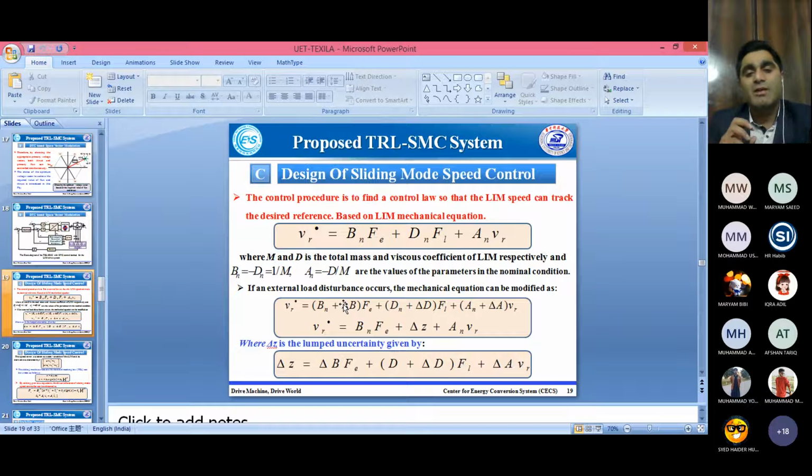So the work of the control law or reaching law is to bring the state to the reference value. So we have to design one equation for the control law, another for the sliding mode surface, so that the sliding state, coming from any state, reaches the rated value.